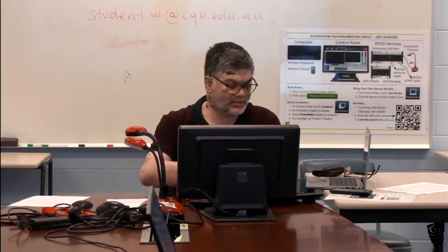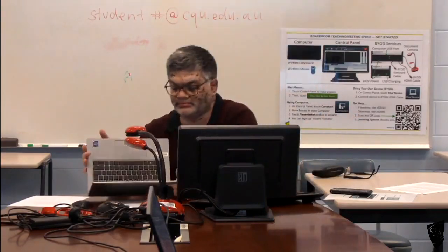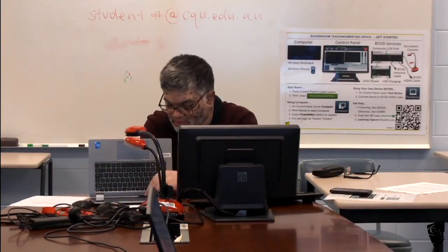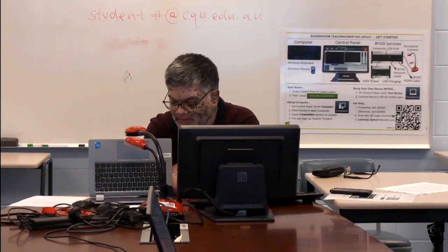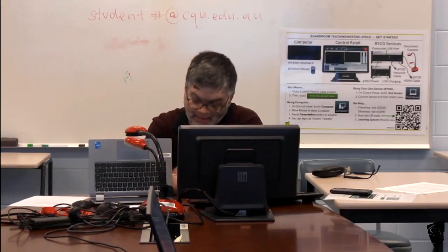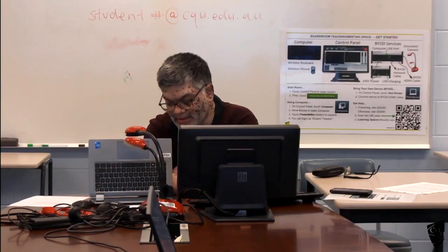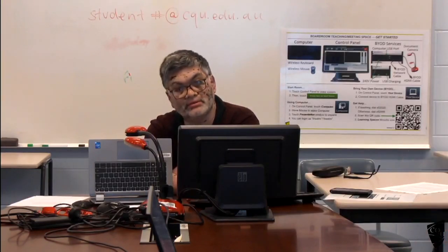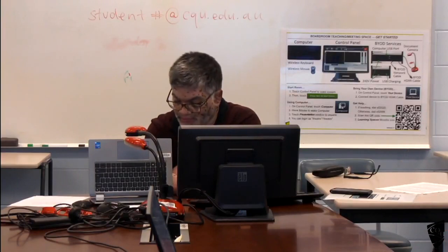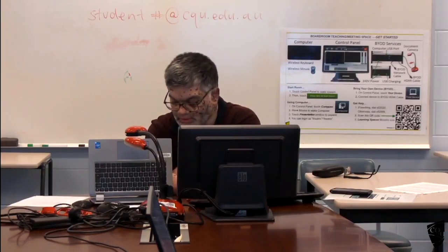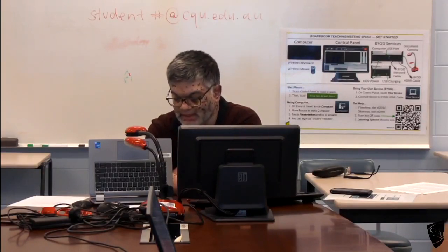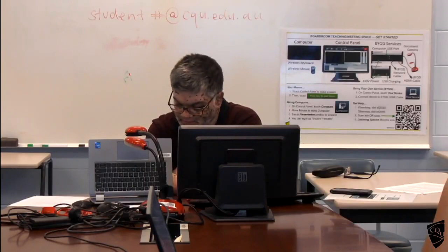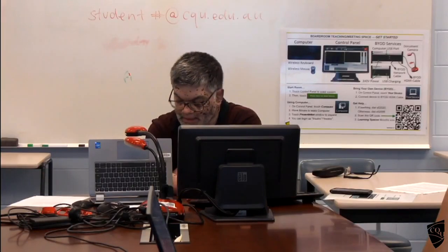Then you go to this table A. So read this one. What is the condition? The flat slab with exterior edges are unrestrained. The flat slab with exterior edges are restrained by columns only. Flat slab with exterior edges restrained by beams and columns. The flat slab with exterior edges are fully restrained, and the beam and slab construction.